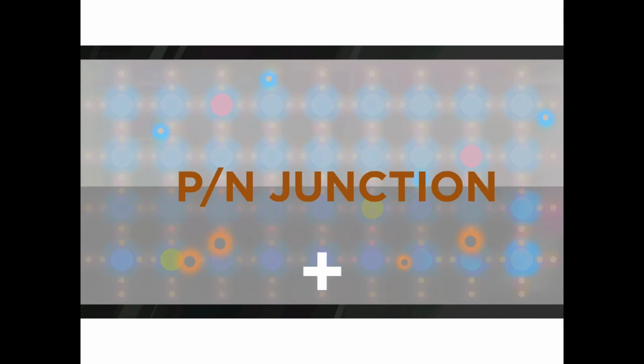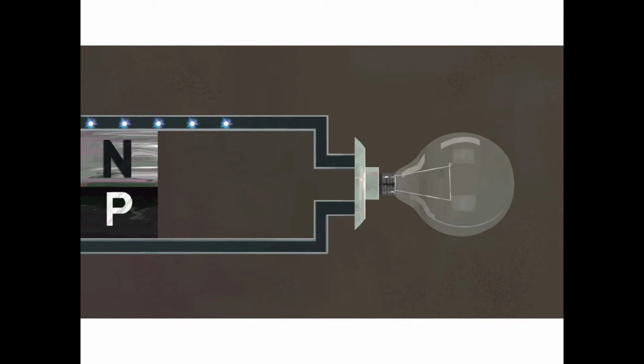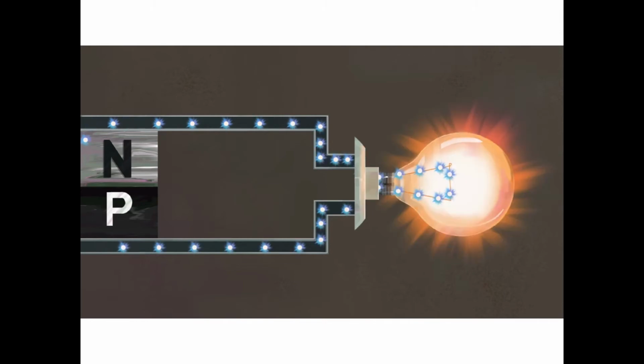You can think of light as the flow of tiny particles, called photons, shooting out from the sun. When one of these photons strikes the silicon cell with enough energy, it can knock an electron from its bond, leaving a hole. The negatively charged electron and the positively charged hole are now free to move around. But because of the electric field at the p-n junction, they'll only go one way. The electron is drawn to the n side, while the hole is drawn to the p side. The mobile electrons are collected by thin metal fingers at the top of the cell. From there, they flow through an external circuit, doing electrical work like powering a light bulb, before returning through the conductive aluminum sheet on the back.